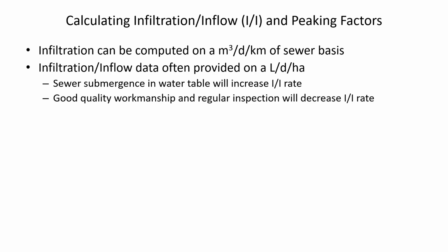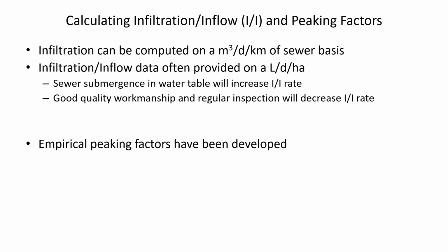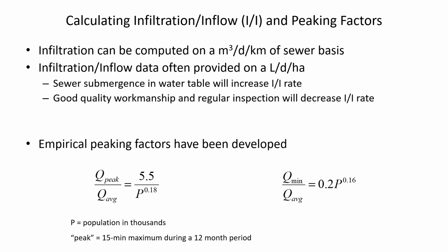But the less frequent the inspection, the more hurried and rushed the contractor is, it's more likely that the bottom slope of the trench is going to have variations, and then over time, as the pipe settles onto that foundation, it's going to crack because there may be a low point in the middle, for instance, that causes that brittle pipe to crack.